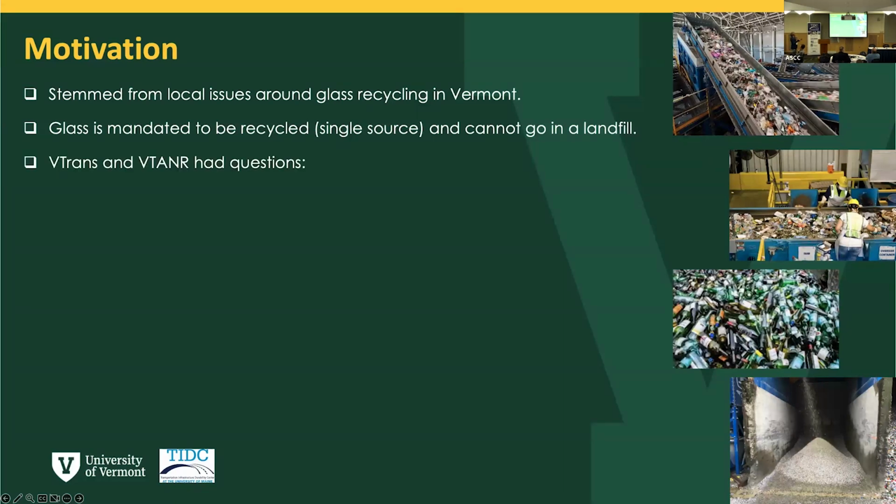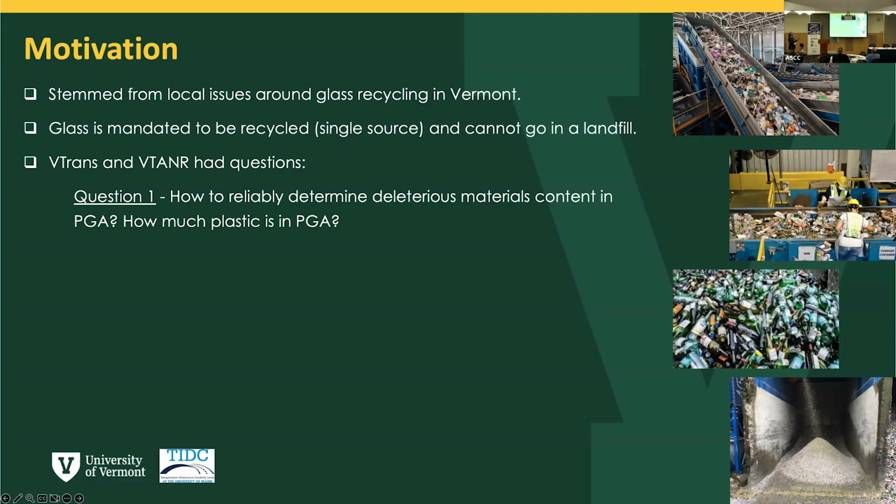So Vermont Agency of Transportation actually has a spec that allows glass with deleterious material up to 1%, and china, like china plates, glasses, cups that make it into the mix, up to 5%. But their major problem is how to reliably determine what is the content of those deleterious materials in the crushed glass.